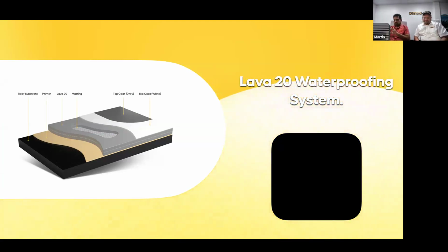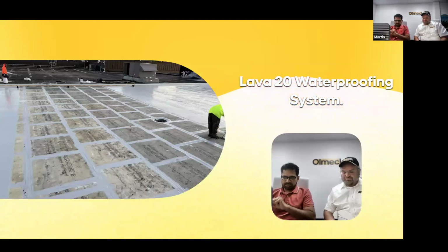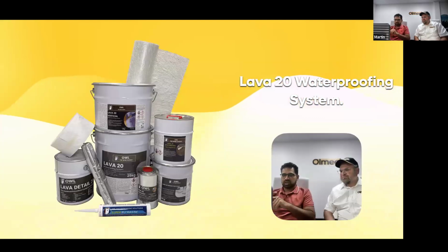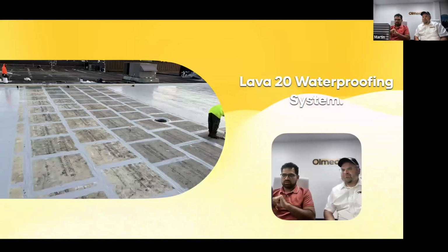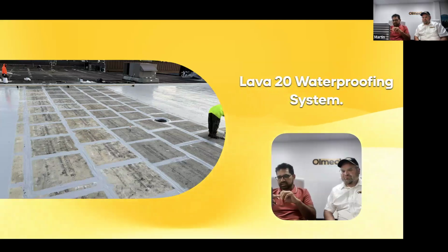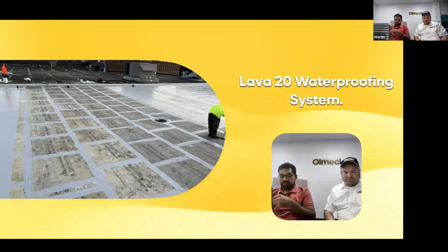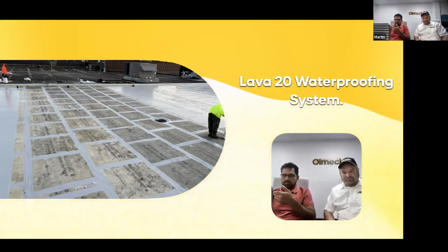With TPO systems, all the customers or building owners have to do, or if they're doing inspections, or a contractor is trying to do a code over TPO system, they just basically do one layer of the primer on top of the EPDM or TPO system, and then on top of that, they will do fleece liquid to get a reasonable warranty from us. Same thing goes for SBS systems. Also, it goes for concrete deck system.